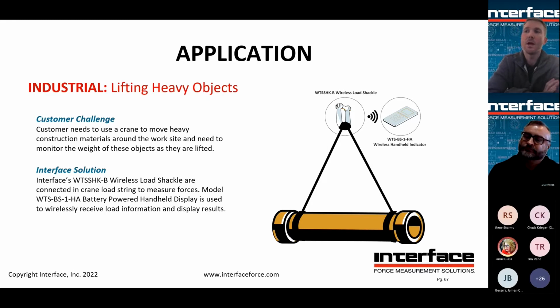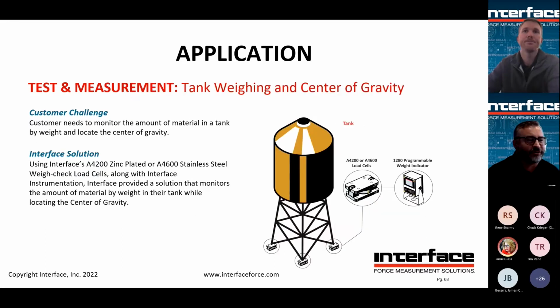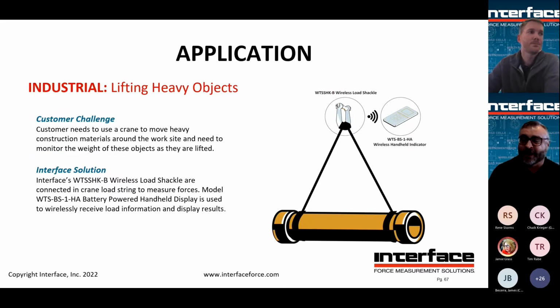Also, a lot of wireless applications. Pair that with a handheld indicator. Make sure you know what you're picking up, so you're not going to hurt the crane, and you're not going to drop it while it's suspended in the air. One point to mention too is a lot of our customers are manufacturing or moving very expensive items. And so one of the considerations when something's being moved would be to monitor, say, tension as you're lifting it, either in single point or multiple points.